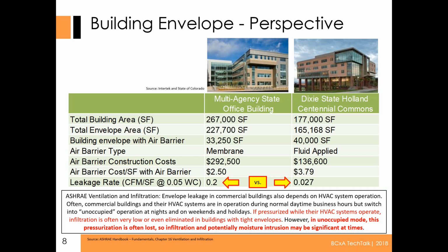The other piece down at the bottom, Ashley's got a nice little quote here, and it's something that we do a lot of in sequences of operations, is we look at having an unoccupied mode or scheduling things off. Well, Ashley talks about when you dial it all in and you get it perfect during normal business hours, you may think, okay, I'm good. Well, when you go unoccupied and the building does something different, have you lost that building pressurization?